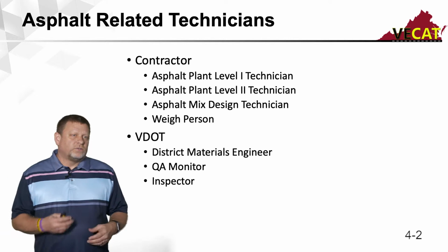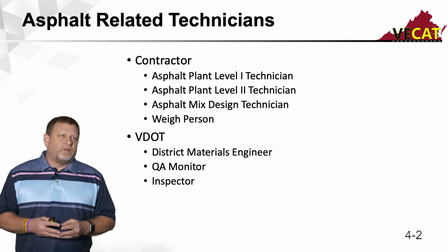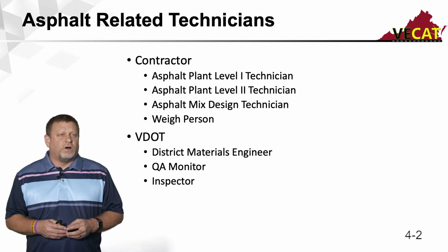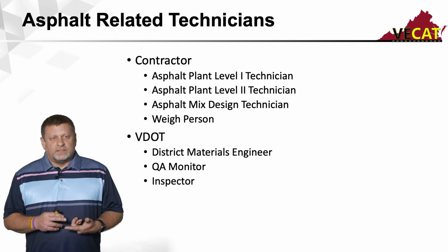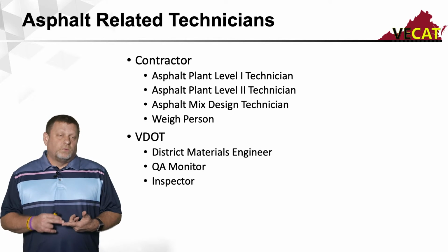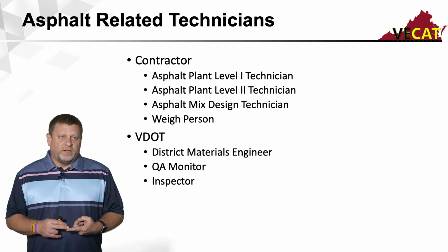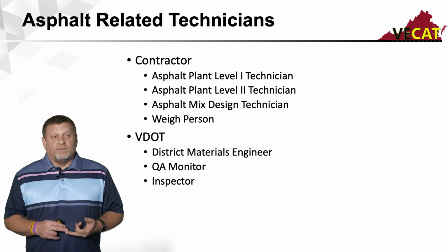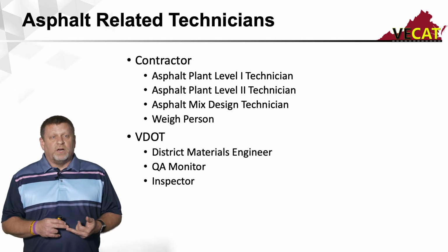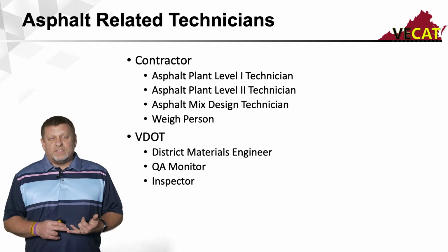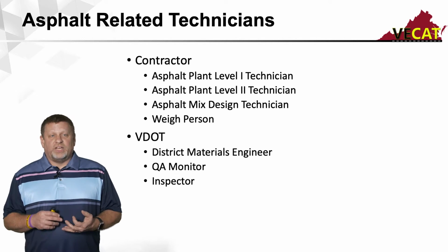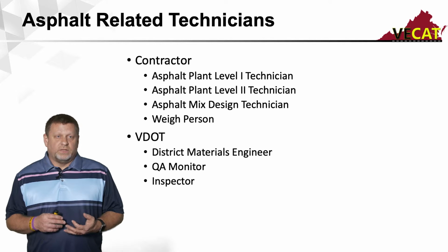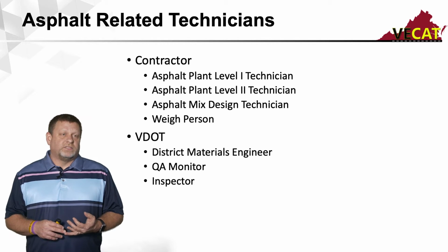The different certifications available here for the asphalt technicians are: for the contractor, you have an Asphalt Plant Level 1 technician. That's the minimum certification you have available, which is required for taking a sample and quartering it down. The Asphalt Plant Level 2 technician is the one that will do production testing. The asphalt mix design technician is the one who does the mix designs and makes any plant changes to keep the mix within approved specifications.